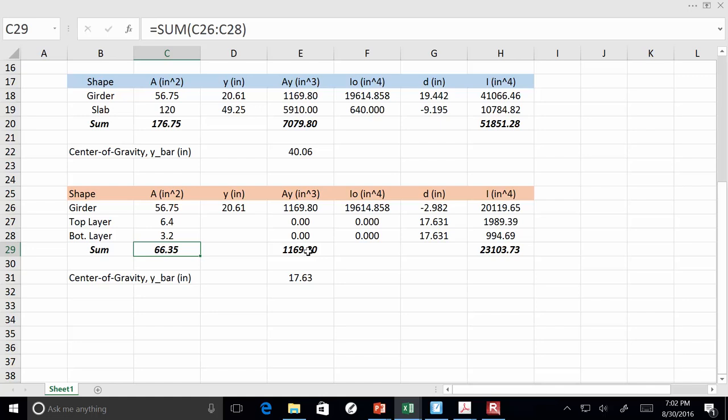Okay. So keep in mind, let's sort of imagine this in our brains. We're going from the datum, which is the way bottom of that section, to where that rebar is, right? So let's imagine. We go up the thickness of the bottom flange, right? Then we go up that web depth, right? Then, if we go up the haunch, that puts us at the bottom of the deck, right? If we go up the structural thickness of the slab, that's the entire height of the section, right? Now, why would I do that? Well, where is that top layer of rebar? It's 2.5 inches down.